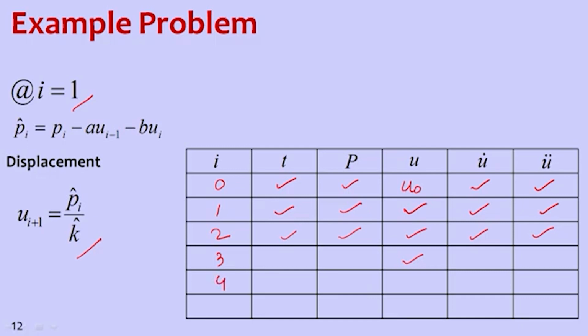So as a summary, we can apply this central difference method to any random signal, which is basically an earthquake force. The most important point to keep in mind is the indexing of the iterations. When we go for a computer program, we need to take care of the i minus 1th value and the i plus 1th value. So displacement will be obtained for one extra value, whereas velocity and acceleration are obtained at the same steps. So i number of steps will be there in velocity and acceleration, whereas displacement will have i plus 1 steps.